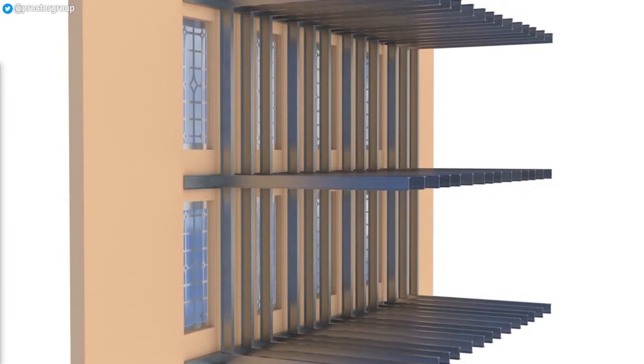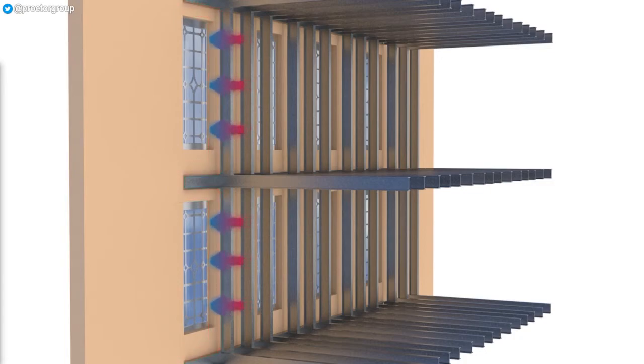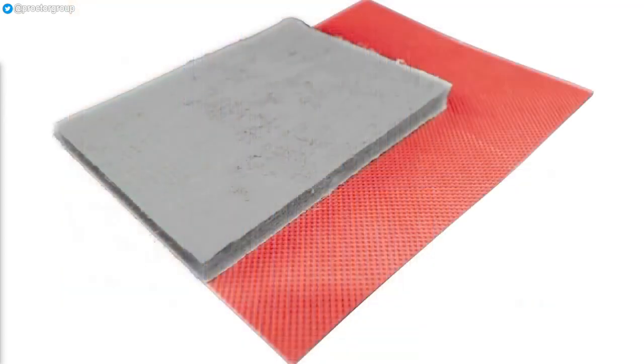While this method resolves a great number of the issues inherent in such projects, by simply replacing the problematic elements and features with modern equivalents, designing an effective interface between what is replaced and what is retained can still be challenging. Air leakage and cold bridging are the most significant problems to be overcome in these areas, so by combining a vapour-permeable, self-adhering air barrier membrane with a layer of high-performance insulation, Wraptherm offers a simple and compelling solution to these issues.